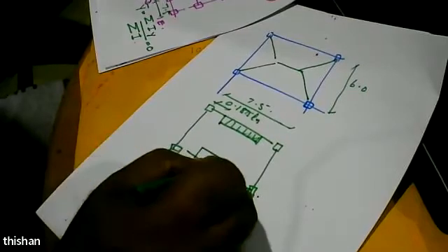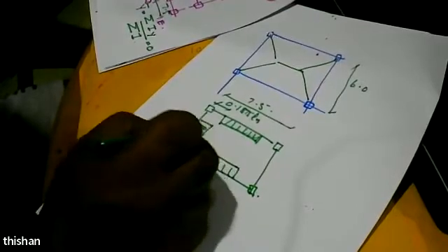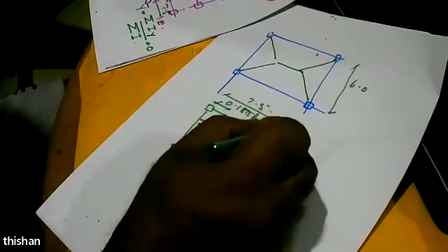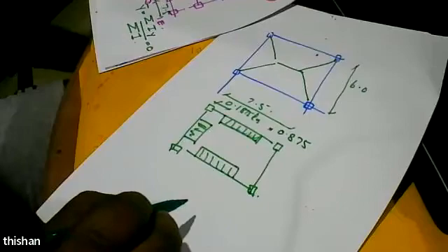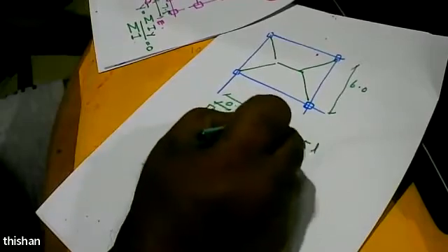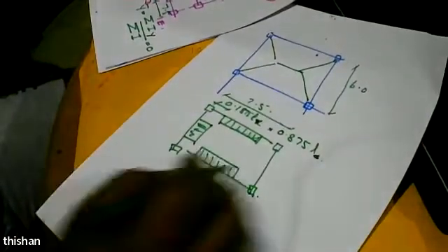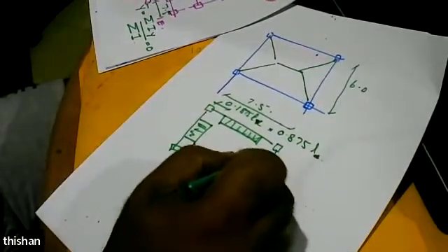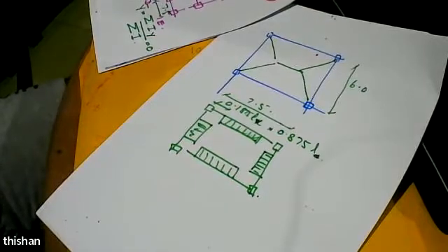And there you say, so here you get another up to 0.875 times Lx. So basically you get the load acting as a uniform load, but the magnitudes are given by the coefficients, indicating how to get the loads on the supporting beams.